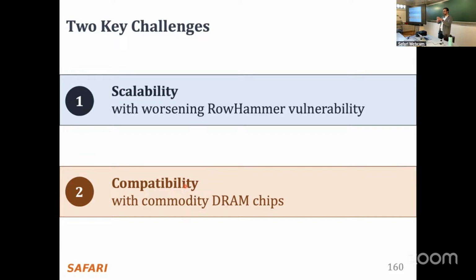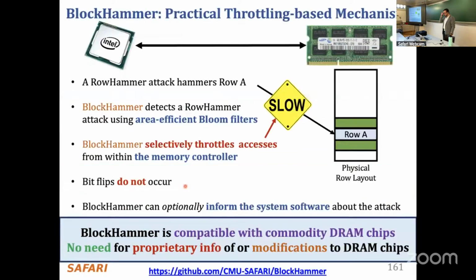You build your computer like Lego pieces, and then you can just buy a DRAM module and put it there as well. And once you get sick of your memory because it's slow or because it's low capacity, you can just swap it out. But your memory controller actually sits in your processor. So when you change the DRAM module, you do not change the memory controller. And if you deploy some RowHammer mitigation in the memory controller, it stays the same once your DRAM module has changed. So your mitigation mechanism in the memory controller should be compatible with as many DRAM modules as possible, right? So this tackles that problem. So before this mechanism, basically, there was something that is not accounted for.